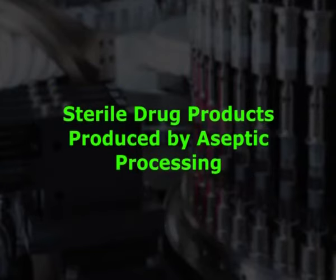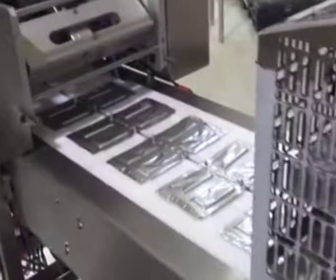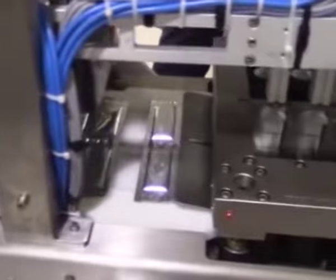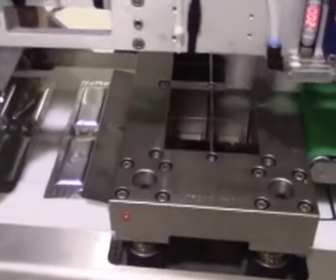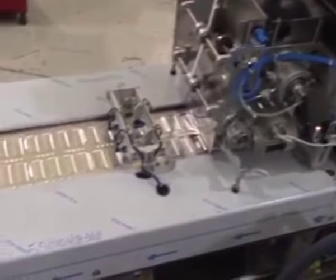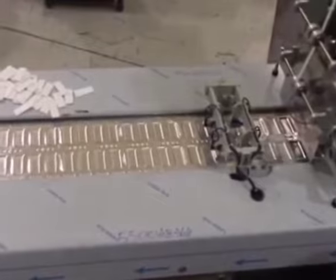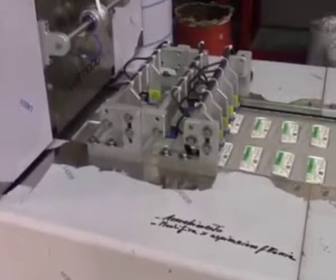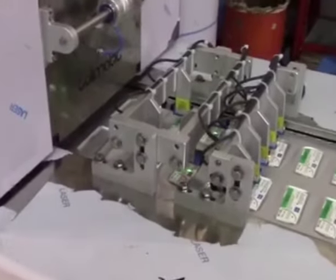Sterile drug products produced by aseptic processing. Let us understand the basic difference between the production of a sterile drug product using aseptic processing and terminal sterilization. Terminal sterilization usually involves filling and sealing product containers under high quality environmental conditions. Products are filled and sealed in this type of environment to minimize the microbial and particulate content of the in-process product and to help ensure that the subsequent sterilization process is successful.